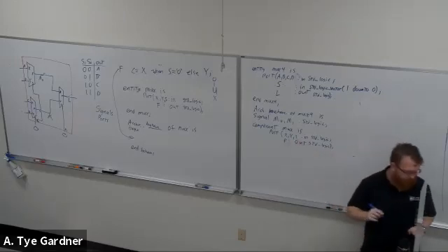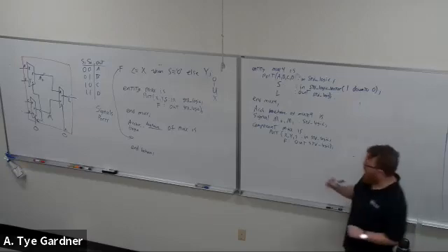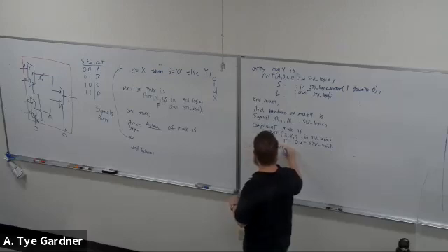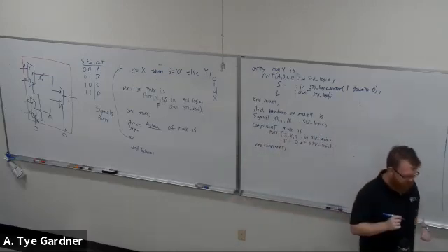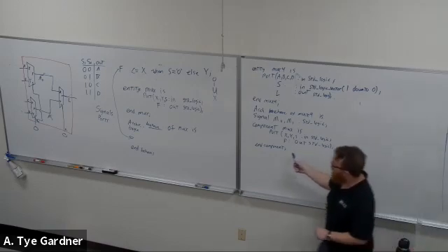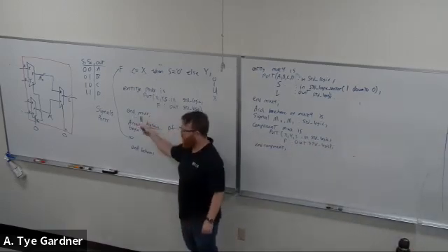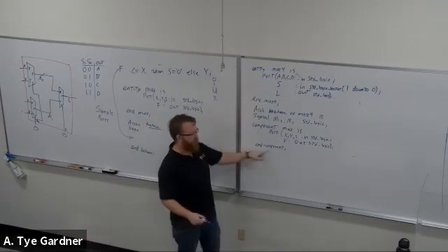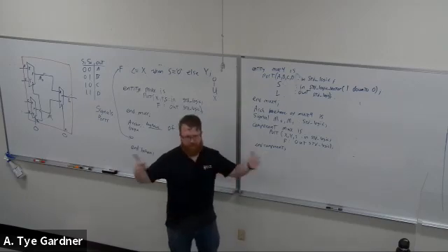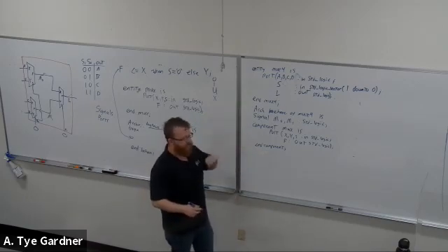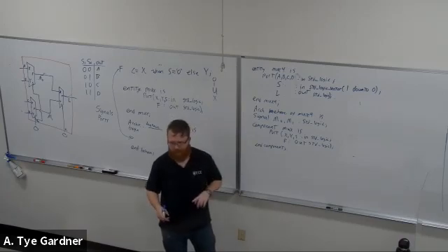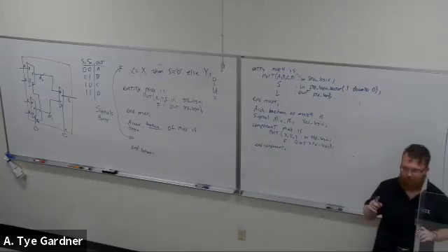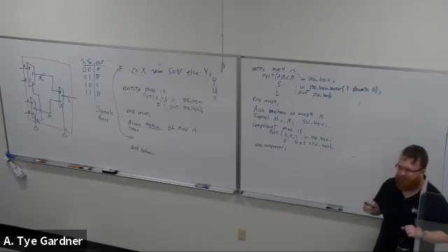Okay, and then this time we say I'm done declaring this component. It's a little bit different, right? Because in the entity, I say entity mux is, end mux. Same thing here, end mux, but for the component it is end component. Okay, so it's just saying that that component exists. There is a reason for that, but I don't want to get into why yet.